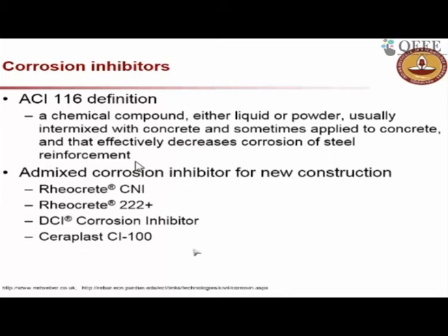Now if you put the corrosion inhibitors into the concrete, that chloride threshold might be increased. Let's say it is increasing by 20%, that means it will have an impact on the initiation time, or in other words, now it will take more time for chlorides to build up enough to initiate corrosion at the steel surface. So the higher the chloride threshold, the more time it takes for corrosion to initiate.